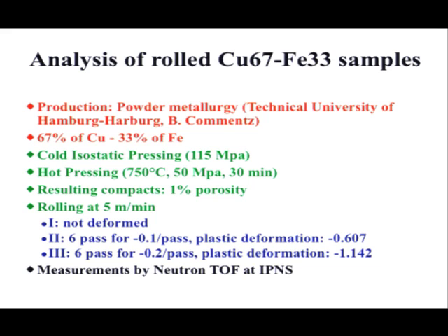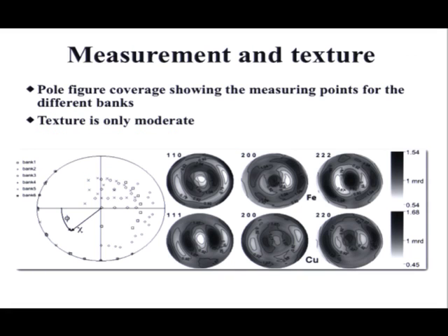Okay, what happens if you have preferred orientation? My way is to try to re-prepare your sample and avoid them. Sometimes you cannot avoid them. So my way is to have a machine that collects several patterns at different inclinations, so I can use a Rietveld texture analysis and get corrected for it. But if you are working with one pattern, then you have to rely on that one. So this was a laminated sample.